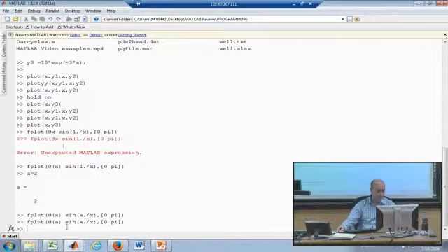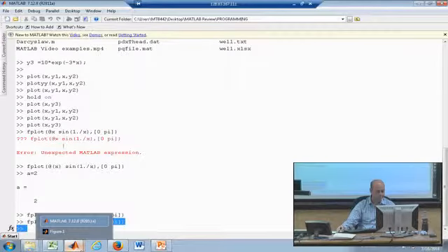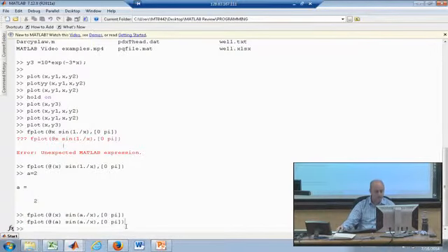Okay, I get something really strange. But the point was that in the first case, I was varying x while keeping a equal to 2. In the second case, I was varying a, and I don't know what x would have been, probably something I defined earlier. But yeah, that's how you use fplot. You can plot just a function and just define the function. I don't use fplot very much. I know people who do, and they claim it's really powerful. So maybe I should be using it more.